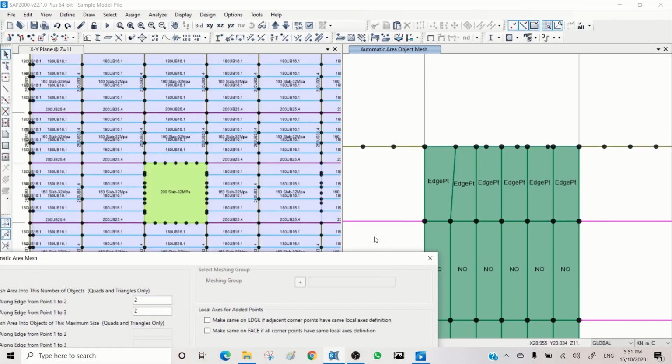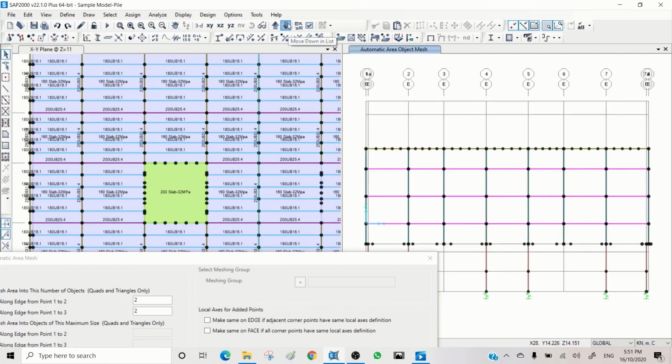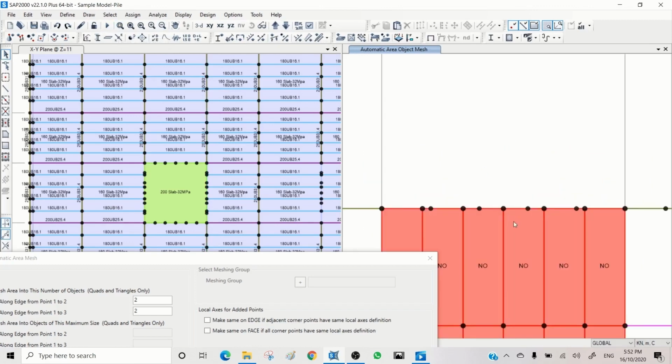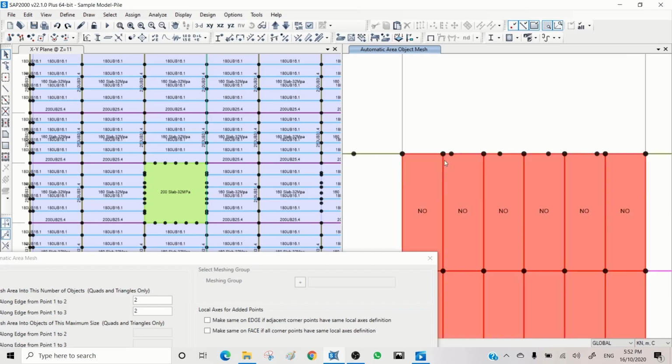The other option we have is adding some beams with strong stiffness to transfer load from these beams to the joints of the shell. So here, if I move back to reach the wall, I don't have any beam here currently. I can draw a beam.